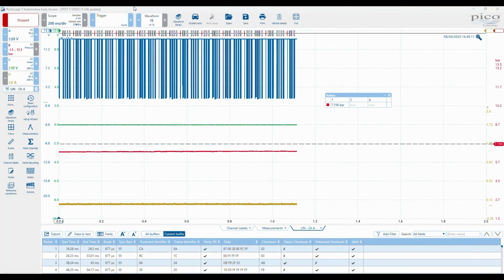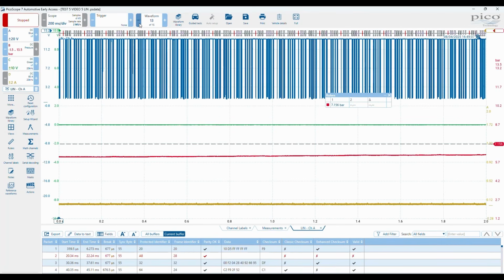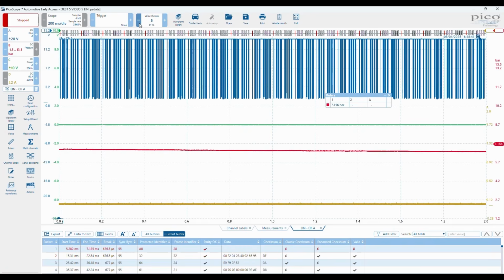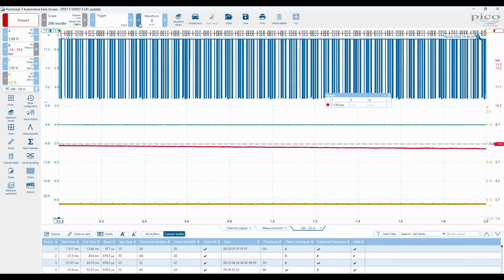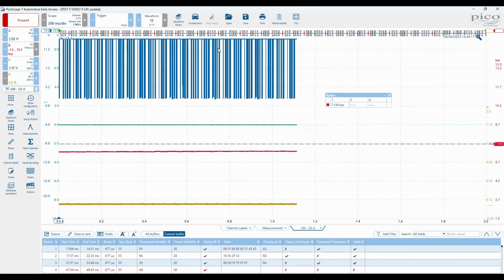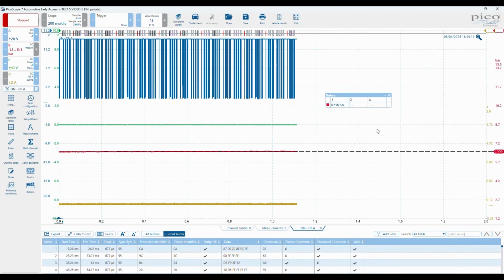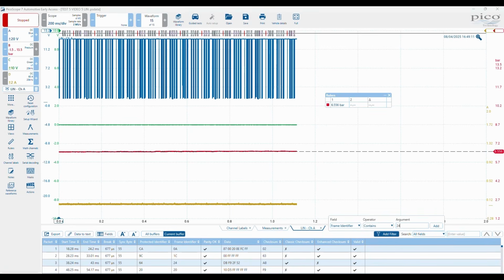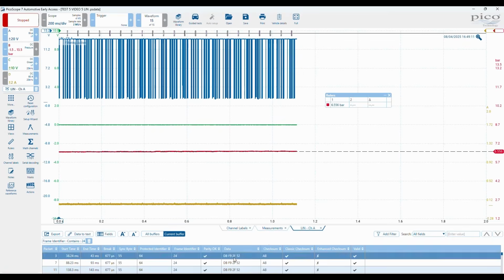So I've now opened the original capture. Remember, the original capture had 15 buffers in there, and I unfortunately took 2 buffers of interest, not thinking about making sure the buffers followed one another. But let's just choose somewhere quite random on here, and let's choose, okay, that's interesting. Let's go for add our filter. We know the frame identifier contains 24, and let's go for this value here, so dBF9.